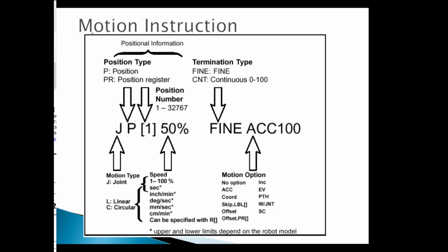Now, that is the maximum speed when the robot is set to 100% speed. Remember that the teach pendant also has speed plus and minus percent buttons on it, so we can change the overall speed. If we were to reduce the speed of the robot down to, say, 10%, then when we ran this program in auto mode, it would be 50% of that 10%, which would be 200 millimeters per second.